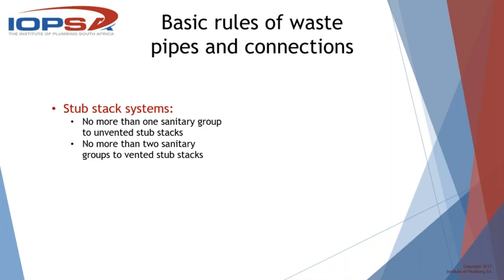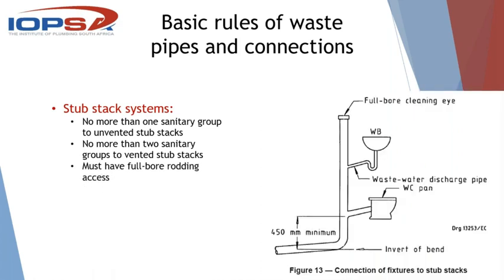That's a different kettle of fish, and Adrian is the guru. So if you have a vented stub stack, you may put 2 groups of sanitary ware. The one thing which is commonly misunderstood about a stub stack is that it has to have full bore access to cleaning.